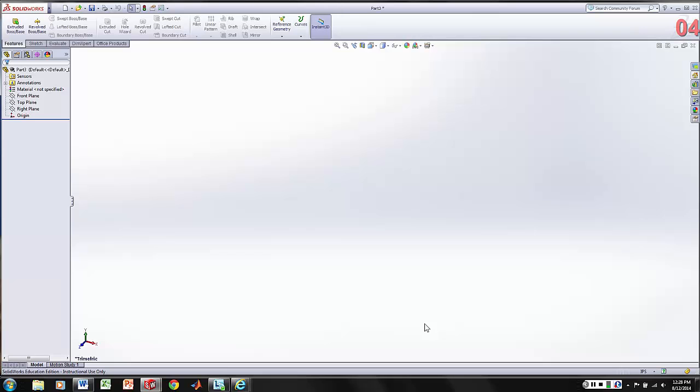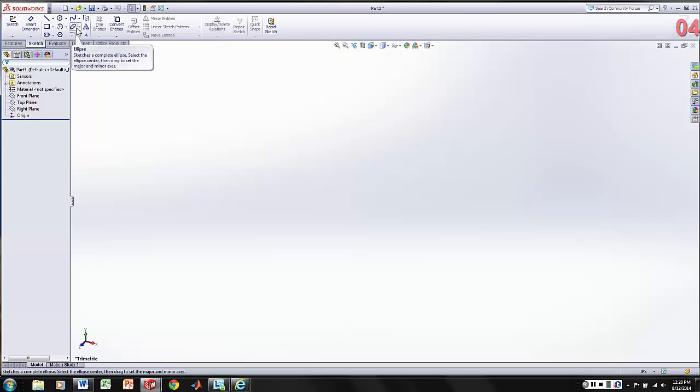Now, the way that one works within SolidWorks is really kind of like if you were going to be talking to a fellow engineer, working with paper, pen, sketching out some stuff, planning. And so the first thing that we're going to want to do is come over to the upper left, click on Sketch, and we have some basic sketch tools. And these should all look pretty familiar with what you guys have seen in AutoCAD. So we can sketch a line, sketch a rectangle, sketch a slot, a circle. We can sketch an arc. Any of these tabs can be expanded, and so we have various ways that we can do that.